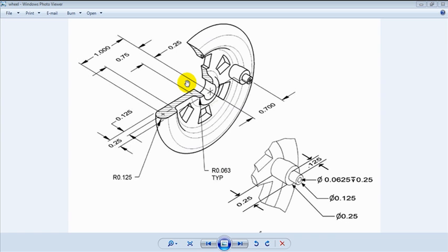Okay, we're going to create the wheel for our train, and so we're going to actually draw this shape right here. This is the shape sectional cut view. A piece has been cut off of this wheel, and if we draw this shape with an axis right here, then we can rotate the wheel around with a revolve, and then we can add the other things to it later. But for now, we're just going to make this shape.